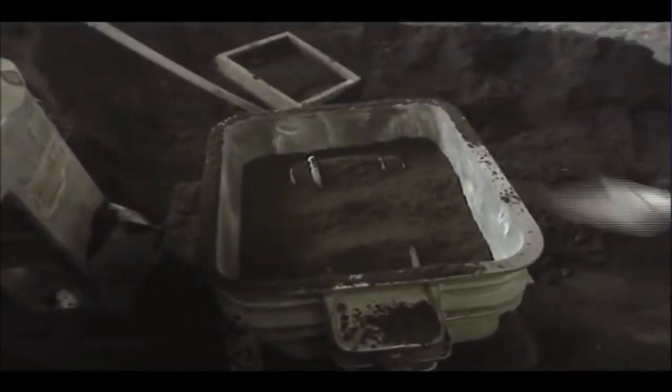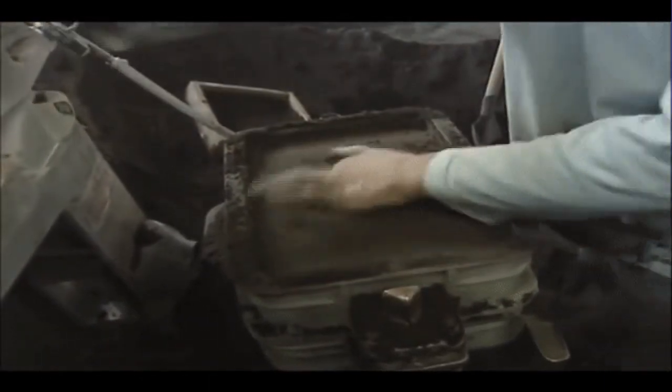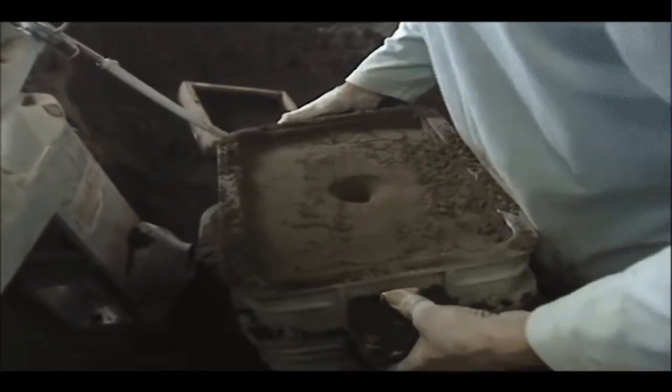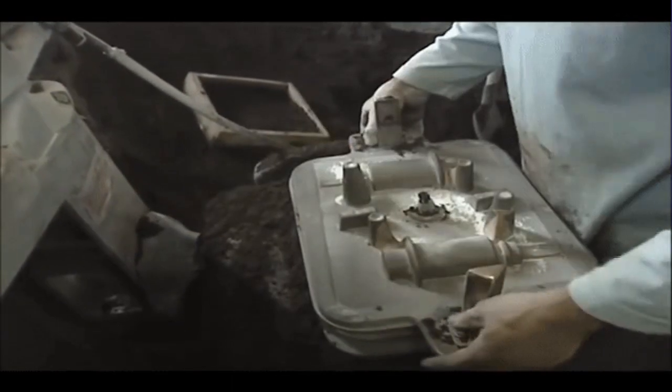Basically, sand casting consists of placing the pattern, having the same shape as the desired casting, in the flask. Start adding the sand that has been prepared earlier to both ends. The sand should be added in a sufficient amount to fill the whole cavity of the flask. Compacting the sand adds some rigidity to the green mold. Incorporating the gating system allows the metal to flow within the cavity of the mold. Removing the pattern creates the mold cavity.